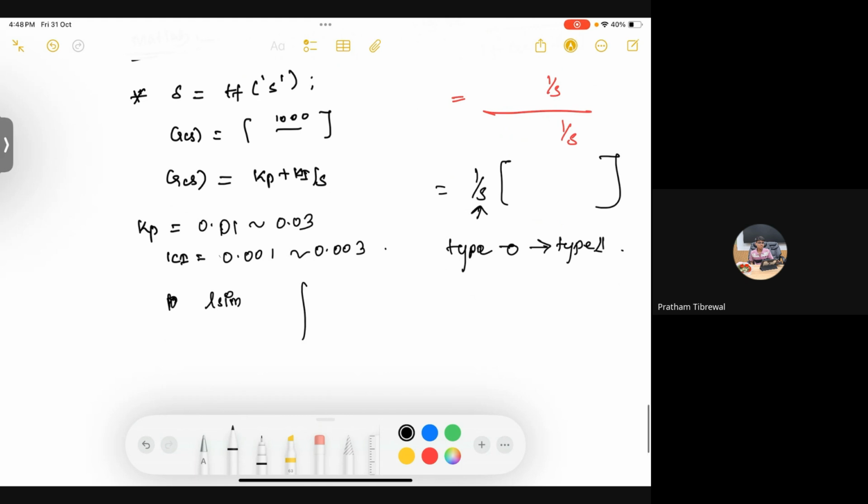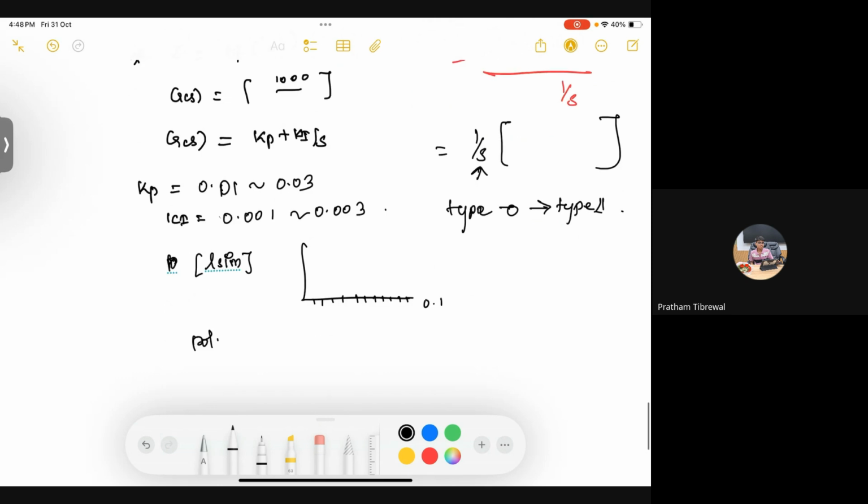Make a plot, use the LSIM command to make the x-axis with time divisions. For example, you can take 0.01 seconds or 0.1 seconds, whatever way you want. You split the time using the LSIM command and then plot the output response of your system, whatever name you call the output variable, with respect to t, whatever you would have defined, t comma c.